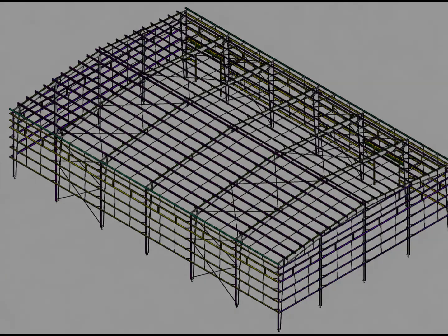So, in this slide, we learned how to trace the sag rod arrangement through a real PEB 3D model. The most important technique is not simply finding a thin line. The correct approach is to start from the approved framing drawing, identify the correct location, find the corresponding framing bay, understand the surrounding purlins or framing members, and then trace the member through the 3D model.